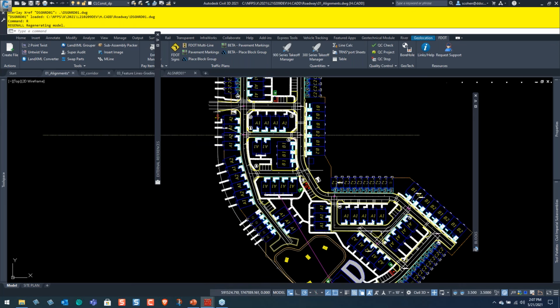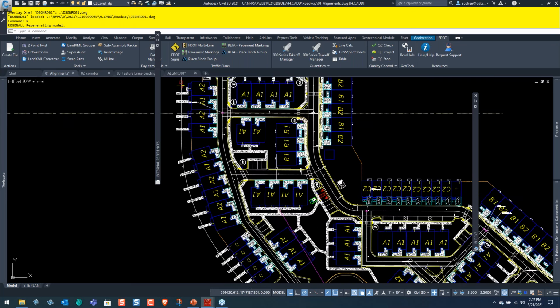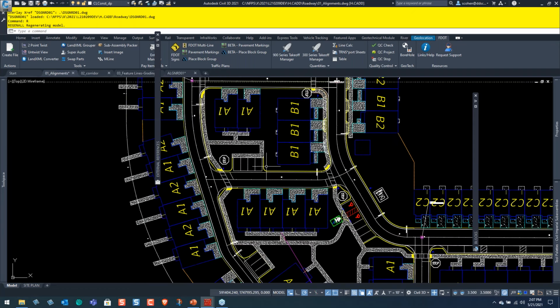So obviously, laying out these roads, there's a couple of things that I want to do. In this case, we decided to not have drainage going to the center of the road, because then your structures are a little more expensive. So we are basically doing super elevation. We're going +2, -2, so that the road drains to one side in all ways. The great thing about Civil 3D is it can automate a lot of this for you, so that when you do modeling, you don't have to worry about any of this, as far as feature lines and things like that.